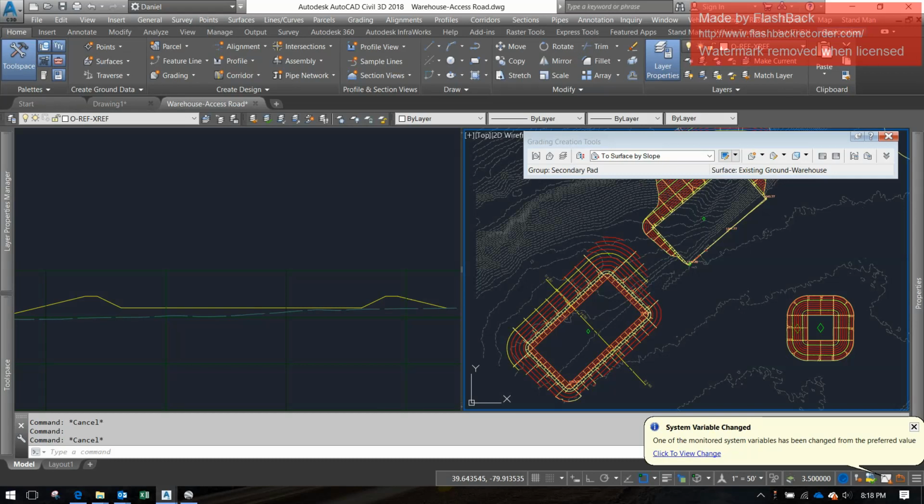But this is very much an engineering problem here, guys. This is a very real problem that you would encounter in a real engineering design. If you think about it, I think my CAD might be frozen. But if you think about it, on the left screen that's a hole, right? And that hole has a certain volume. So typically what you'd have to do is determine the volume of the fluids that you're trying to contain and design a berm that's high enough to contain those fluids were there a rupture in the tanks.